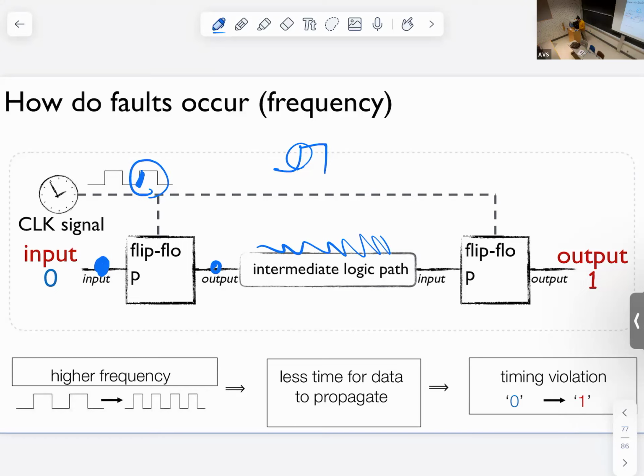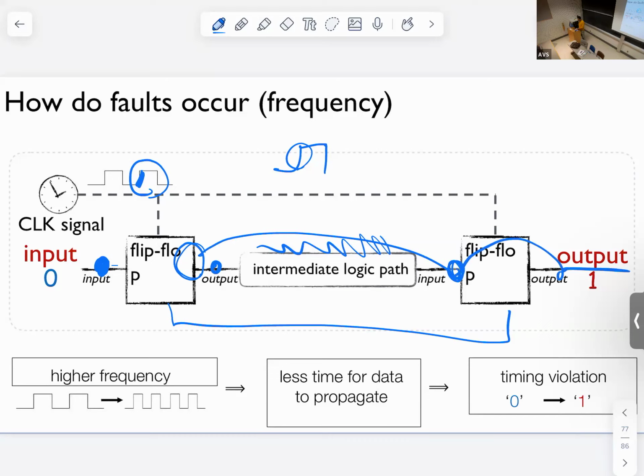And we typically sandwich this combinational logic between two sequential elements, so you can think about this as a kind of task. Data comes, it's stored here, it goes through this, and then comes here and is stored in the next cycle, and goes to the next one. So we create this pipeline-ish behavior where things go between two flip-flops, do some activity, go to the next pair of flip-flops, do some activity, and move forward. That's usually how we design circuits.